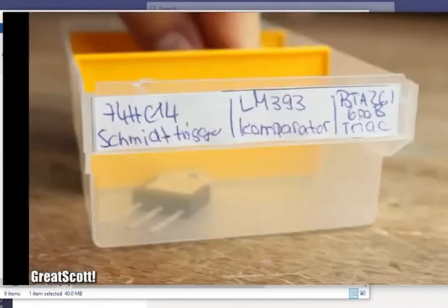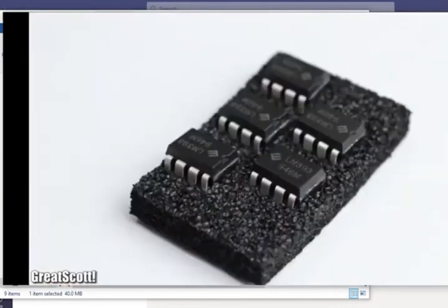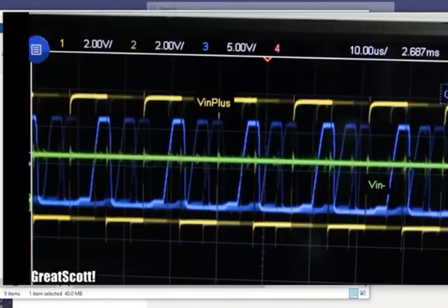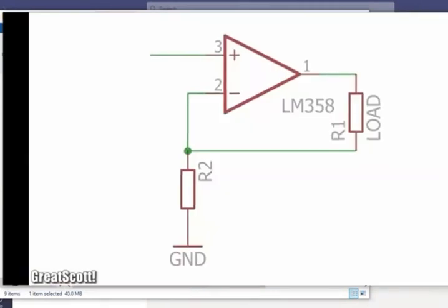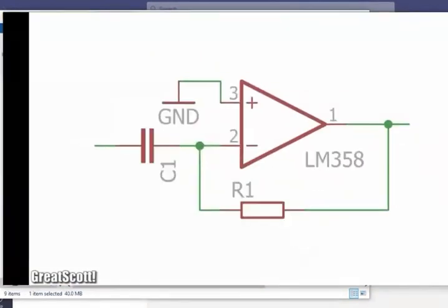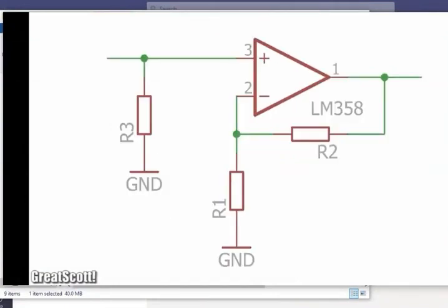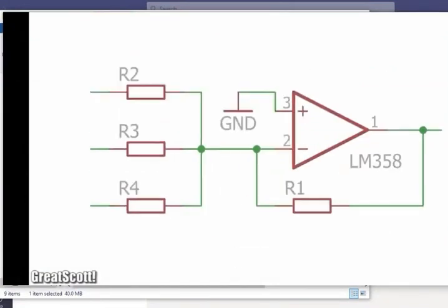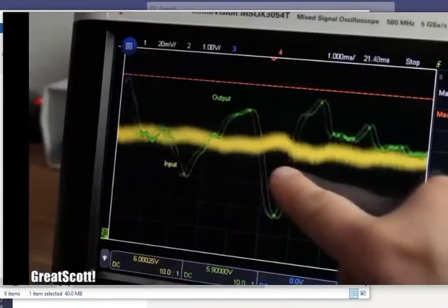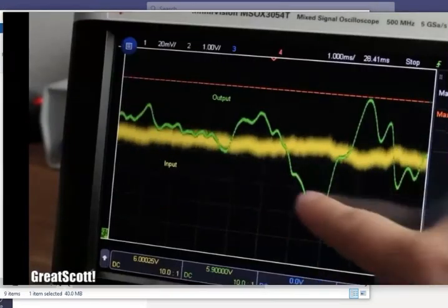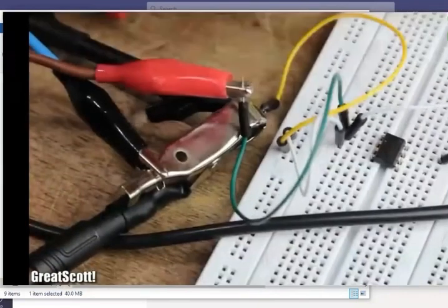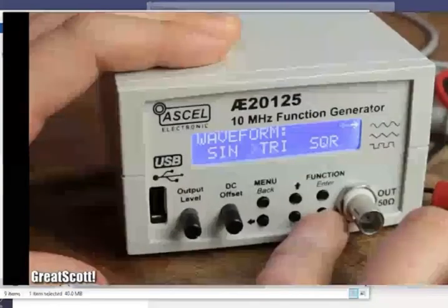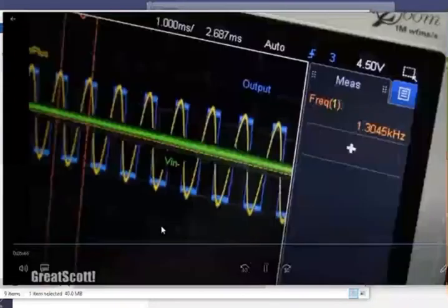And there also exist separate comparator ICs that achieve a faster response time than the average op-amp. And with those three golden rules in mind, you can understand and build constant current sources and loads, voltage followers, integrators, differentiators, inverting, non-inverting, difference and summing amplifiers, Schmitt triggers, and the list goes on and on. As you can see, it is a versatile component and there's much more to say about it than what I just presented. But that is a subject for another video.